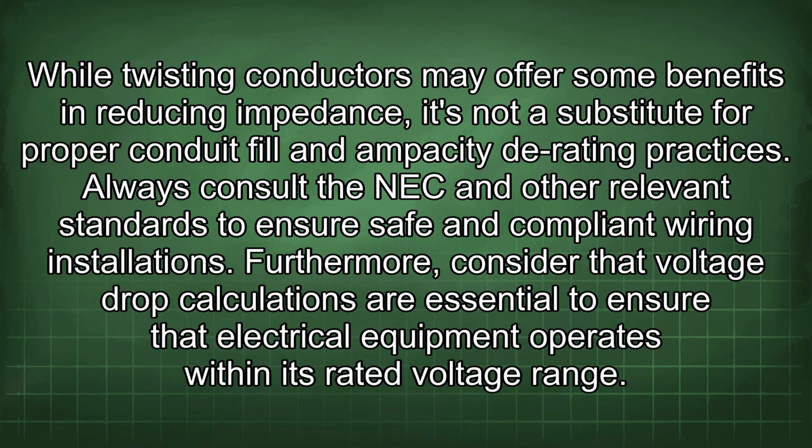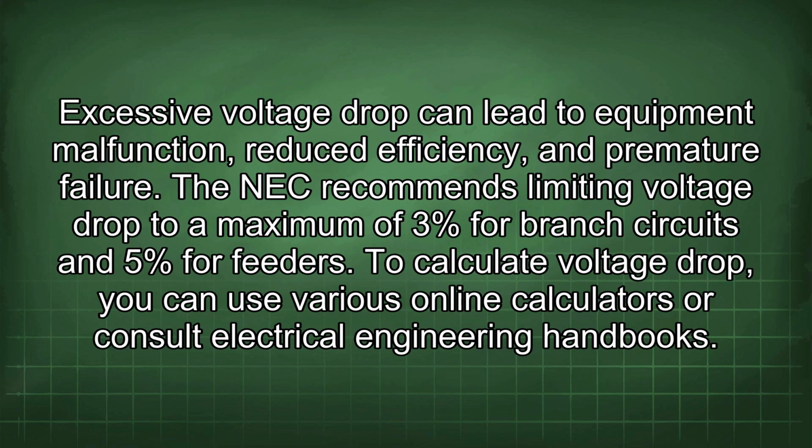Furthermore, consider that voltage drop calculations are essential to ensure that electrical equipment operates within its rated voltage range. Excessive voltage drop can lead to equipment malfunction, reduced efficiency, and premature failure. The NEC recommends limiting voltage drop to a maximum of 3% for branch circuits and 5% for feeders.